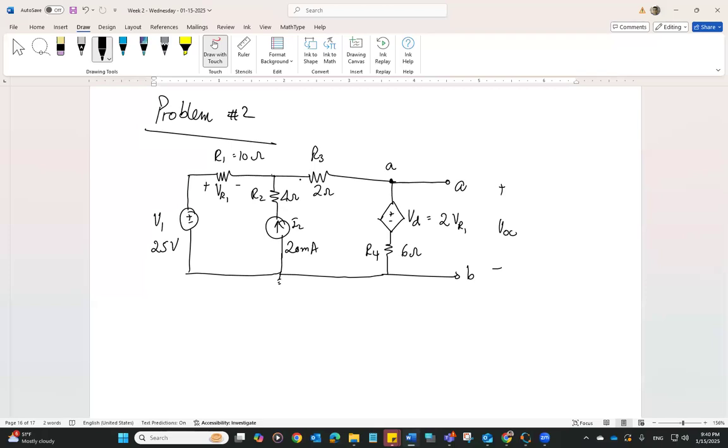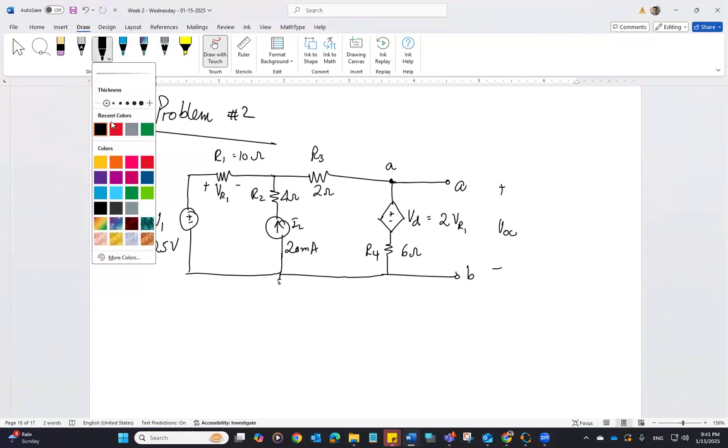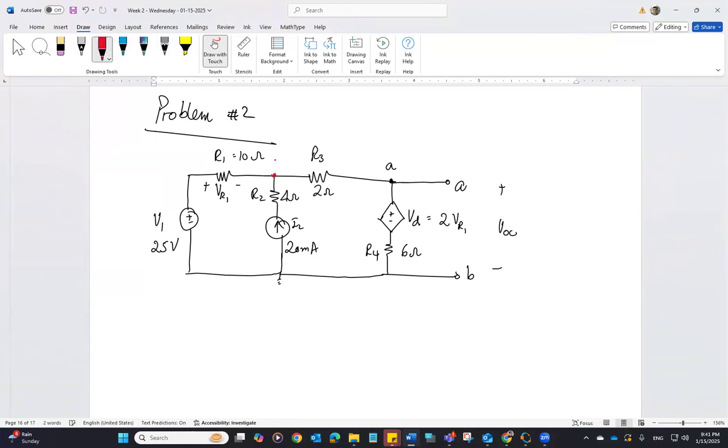The current that is passing through R3 is just going to go to VD and R4, whichever direction you want to take that current, but it will basically be a single branch because no current can flow towards the load. We have removed the load, or we did not really put the load, but if the load is here, we have to remove it and keep those nodes open. So we can assume that we have this node, I can call it node C since we already have A and B. We can find the voltage at node C, and let's call this VC.